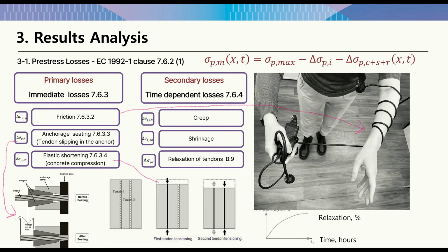If you move the tensioned end to the side of your hand, like that, in other words, you imitate the anchorage slipping by a few millimeters, the tension at the hand will decrease here. But you can feel closer to the middle of your hand that the pressure force has not changed much. And this difference is again caused by friction.